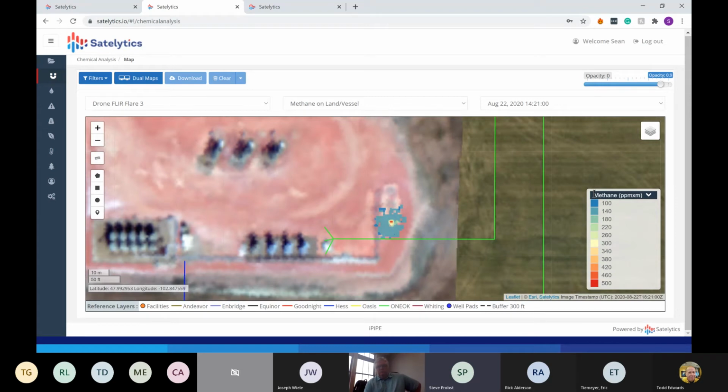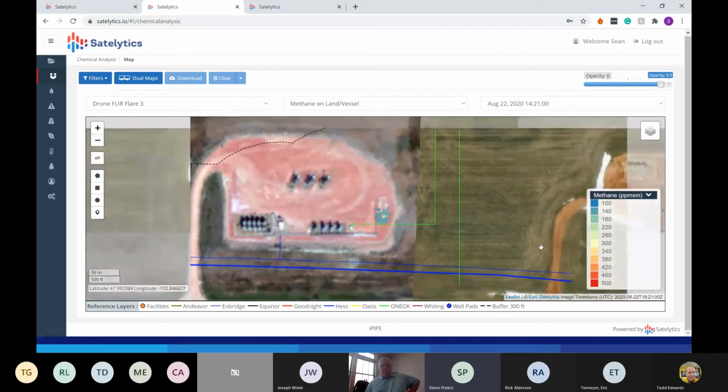Instead, the mechanical breather vent valve has jammed, and so now the tank is venting all the time. For a company to see that, there would be safety issues with getting up on top of the tank.